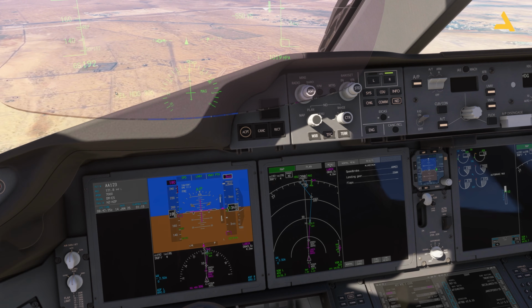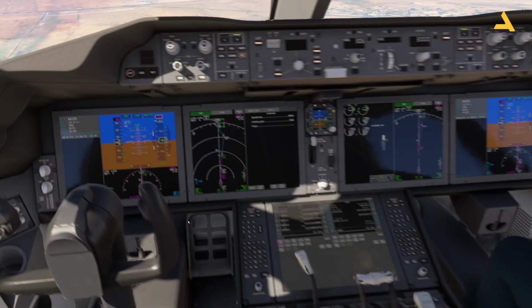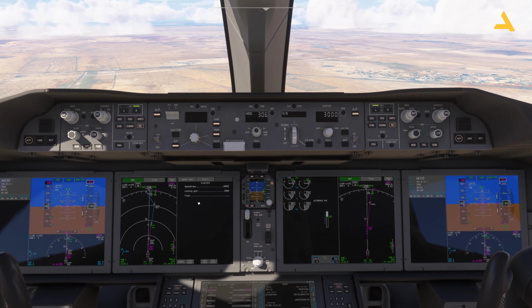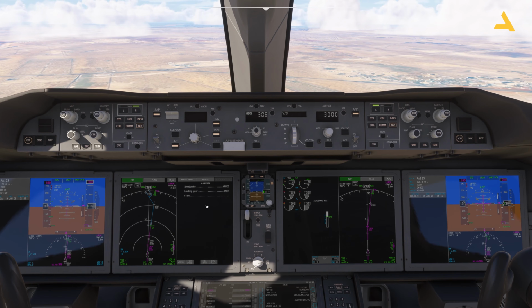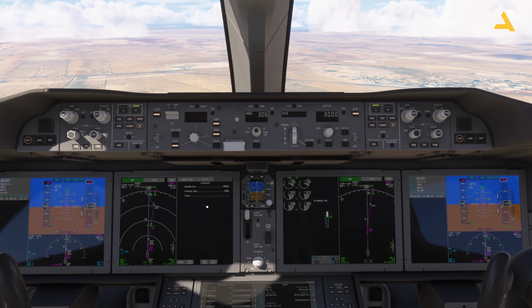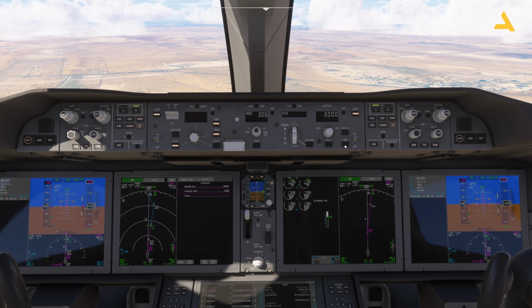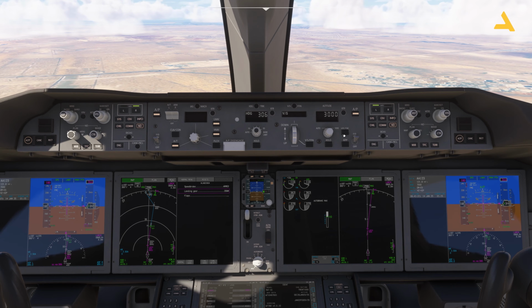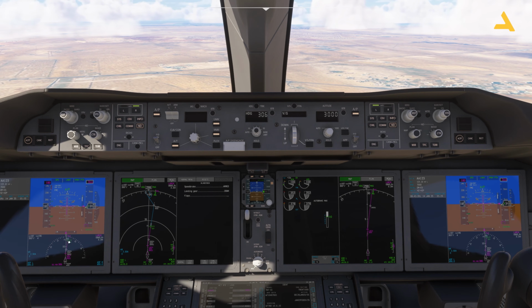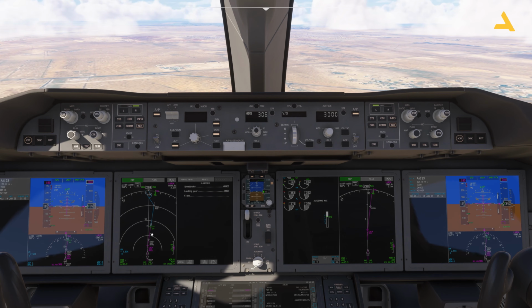That's it. I can just close this window. And now, in order to perform this ILS approach, you have two options, localizer and approach. If you only press localizer, then the plane will do this lateral alignment with the runway.